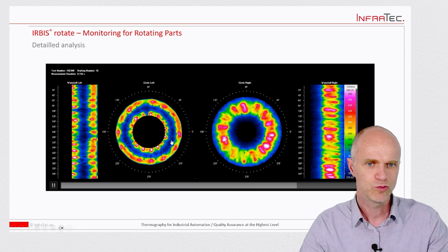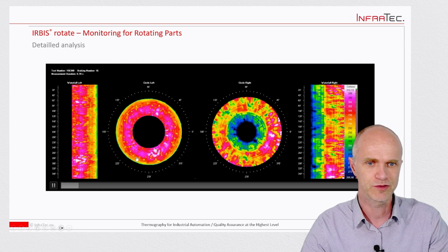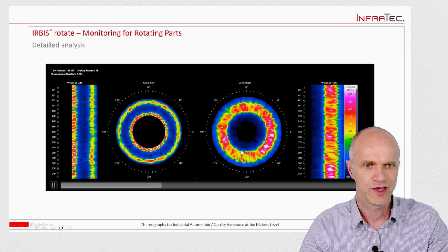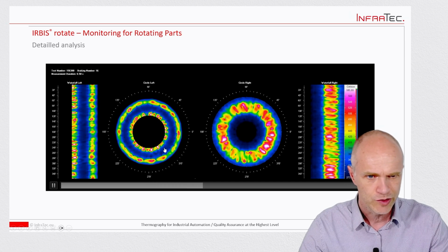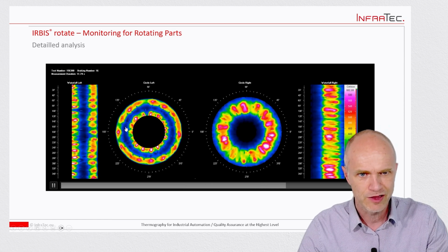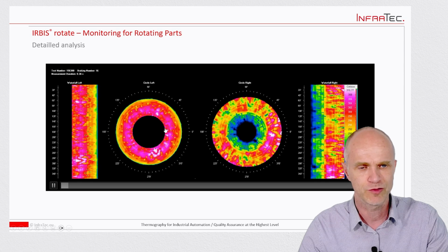And finally, what you want to have is a homogeneous temperature on the brake disc for braking, and not just hotspots. Like you see any critical point here. You even see the cooling holes of the brake disc. So this little small holes here in the brake disc are the cooling channel of the brake disc.